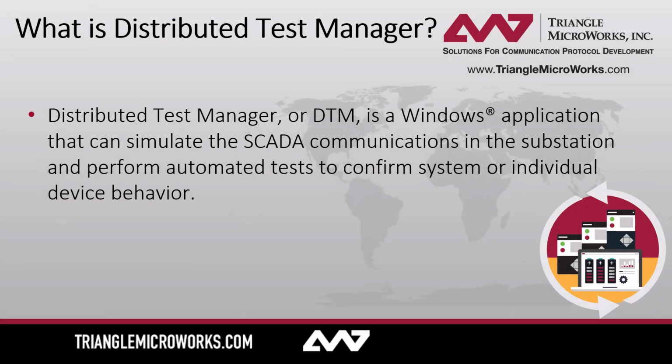Today, we will be talking about Distributed Test Manager, or DTM for short. DTM is a Windows application that can simulate SCADA communications across an entire substation or at a device level. It can also be used to perform manual or automated tests to confirm the behavior of these devices.